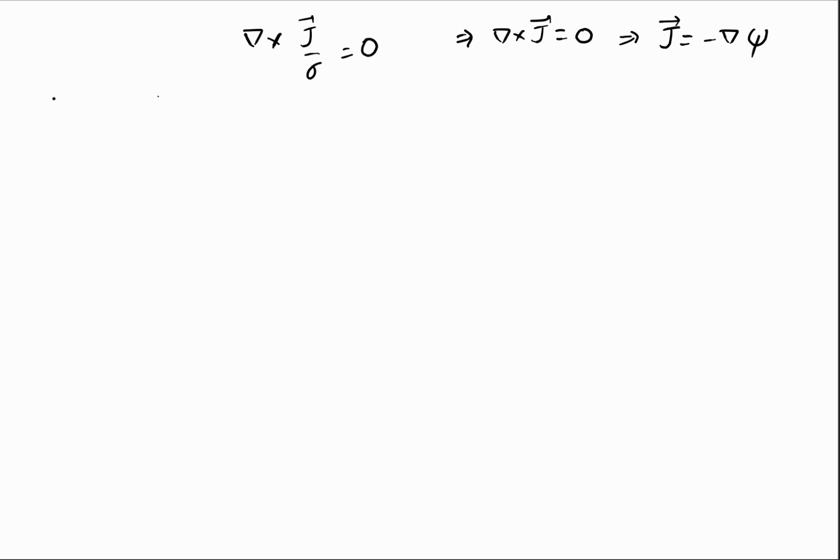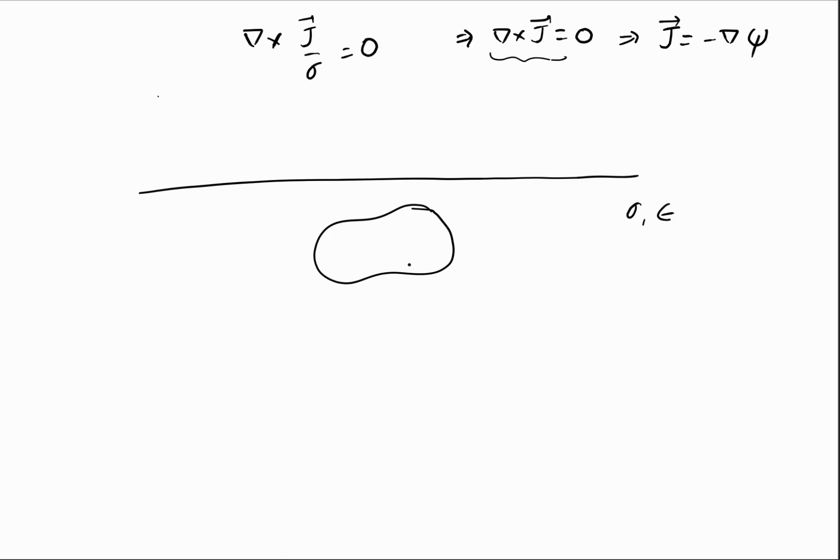So the method of images, which is applicable for electrostatics, should also be applicable for the condition having a homogeneous media with steady currents. So let us assume that ground is homogeneous media. Of course, practically it may not be the case. So we are assuming that this is ground with sigma, epsilon as material constants, and there is a ground electrode which is buried in this soil.